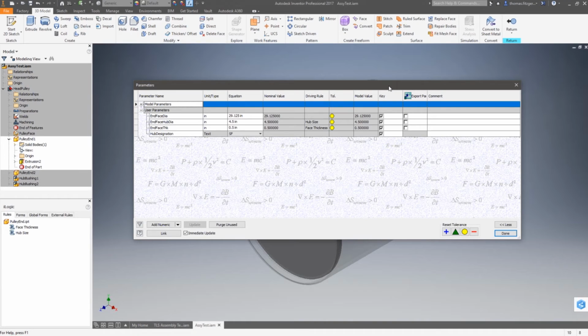And a month ago, when I gave the first webinar, I had discussed data sources, where I said Excel spreadsheets can be data sources and Access databases can be data sources. Well, Inventor files can be data sources as well, because they store information. They have placeholders. You can put information in and reuse or access that information as necessary.